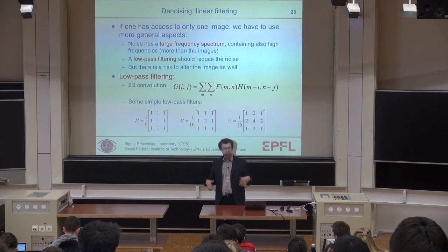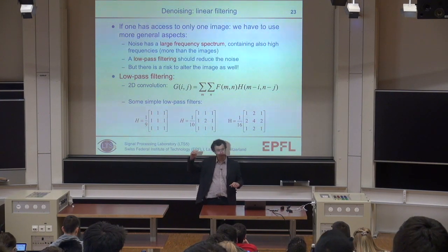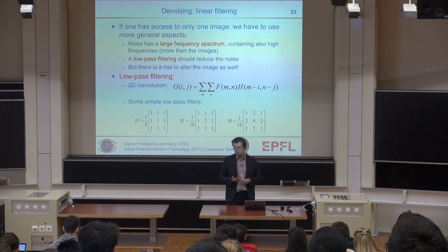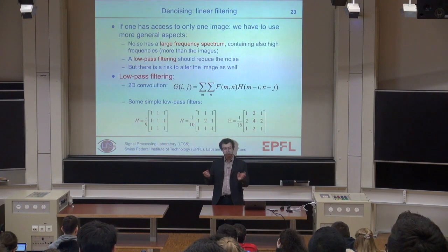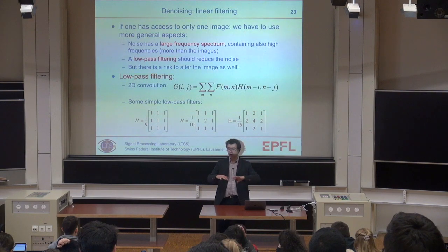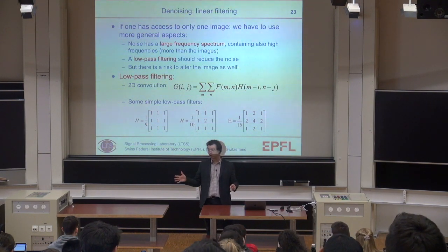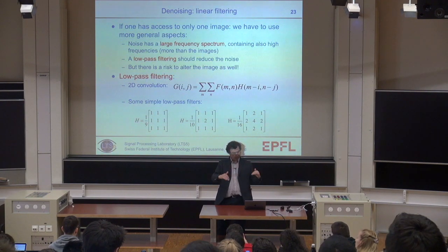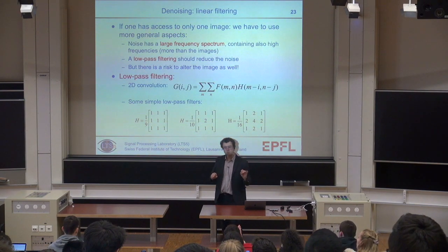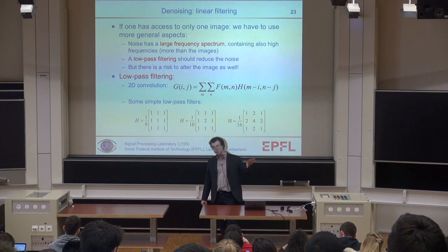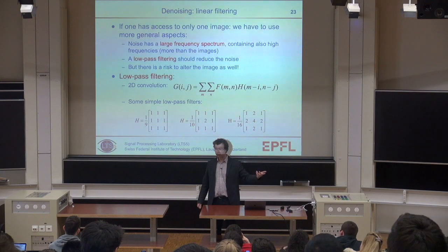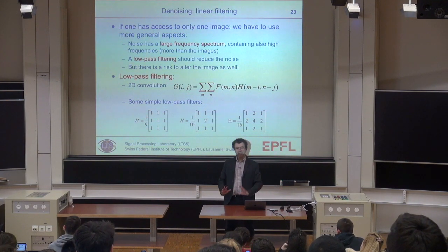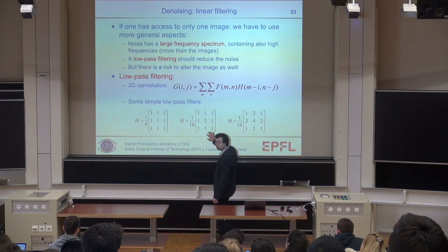Now let's compare that to the spectrum of a natural image. Take a picture, maybe not of the scene that you have in front of you, but of a natural scene outside. What do you expect from the spectrum of this natural scene? Not much, probably, but at least there is more low frequencies than high frequencies. You have lots of very uniform regions, very low frequencies, and sometimes here and there you have high frequencies when you have sharp transitions, right? So compare a spectrum of a natural image, which is more or less on the low frequency side, on top of which you have the spectrum of your noise, which is uniform. What would be a good way to reduce the amount of noise is to filter the high frequencies, because you will remove a component of the noise where you have a lot of energy, the high frequencies, and you might remove a little bit of the image, but hopefully there is not too much high frequencies in your image. So the very naive 101 filter for denoising is to use a low-pass filter.